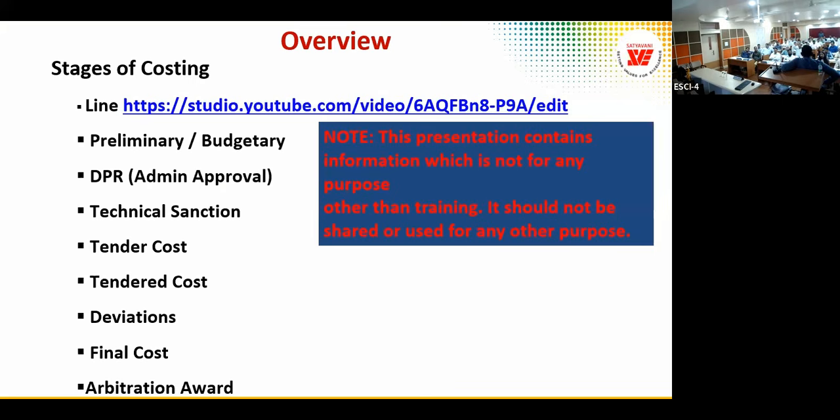No, sir, for preparation of DPRs, the rates that we have to obtain from the agency are kept vacant. Only the cost estimate is there. After getting the rates from the EPC contractors or the EPC bidders, the final administrative approval is given. Sir, actually, you cannot take a market variation index during the currency of the project. Only after completion of the project can you take a market variation index. The contract becomes complete only after completion. Because if you say that you will revise your technical sanction and your estimate based on the EPC quote that you receive, that is wrong actually.